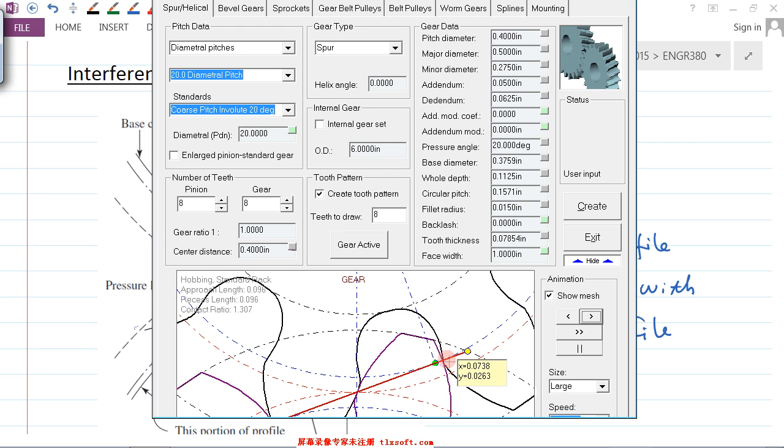So if I move this a little bit more up to this location, imagine what happens. If I draw a straight line from here to the center, then this portion of the involute is going to get in contact with this straight line, right? So if you see, you draw a straight line right here, and guess what? It's going to contact this portion of this involute, right? This is involute. So it's like an orange getting to contact an apple. They don't like each other. So when they don't like each other, the bad thing that happens is this orange will try to dig into the apple.